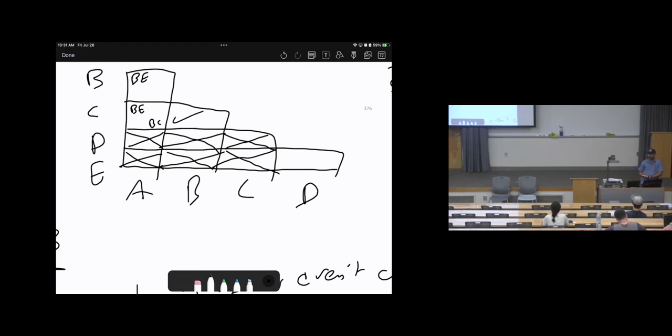Okay? So here, when I put a check mark, I'm 100% sure those pairs B and C are equivalent to each other. So our target in this implication table is to find all of the equivalents at once. We will not do the first one and redo it again and again. So we'll do all of the simplification at once.